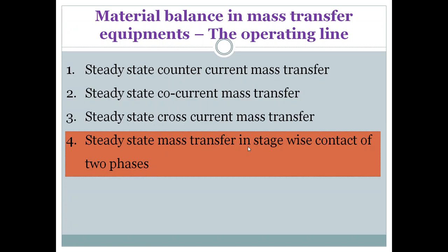In cross current there are three units, but these are physically separated units. If you make three physically separate units, then you are getting better mass transfer because you are attaining the equilibrium three times. But is it possible in a single equipment to make multiple equilibrium stages, or create multiple equilibriums? If we can, then I will get better mass transfer.